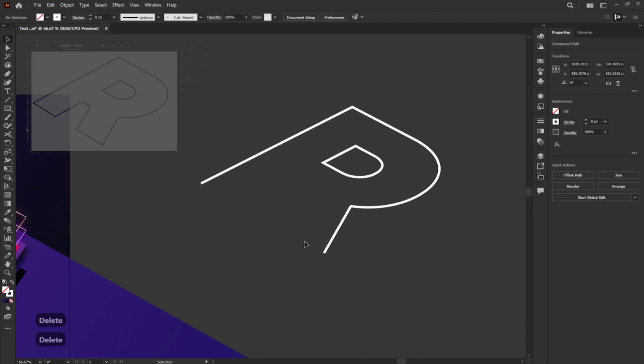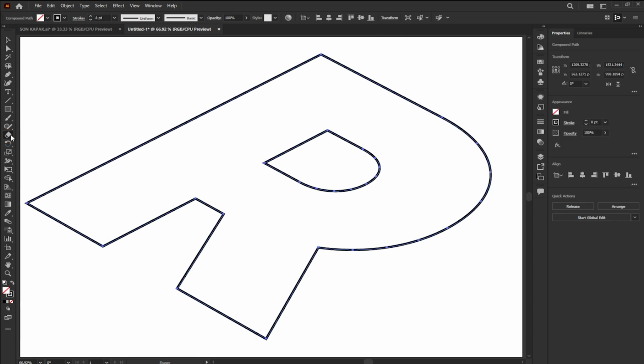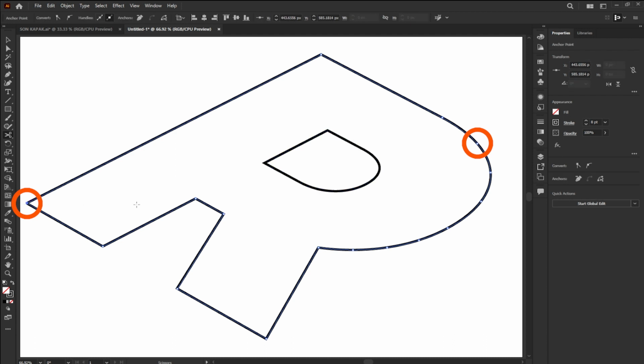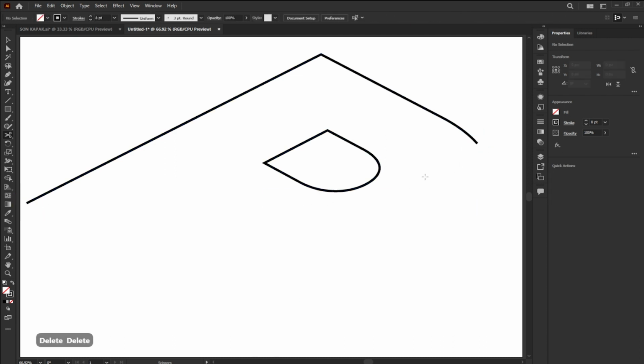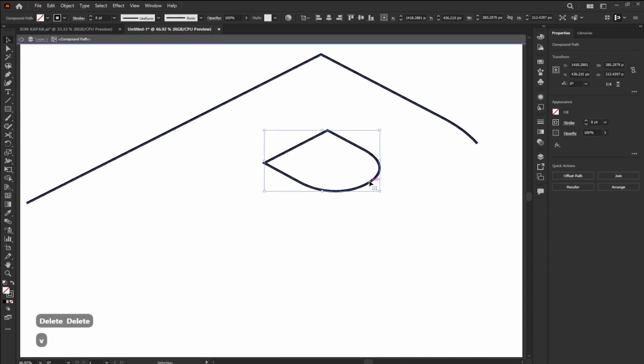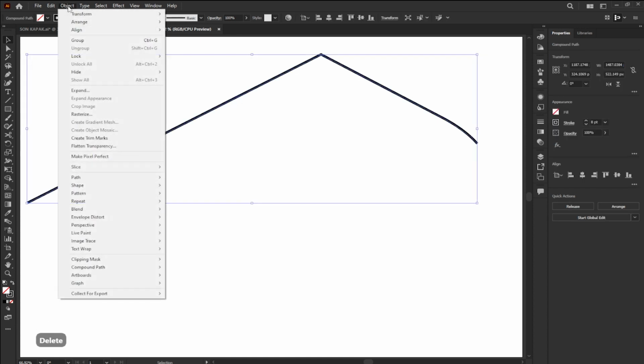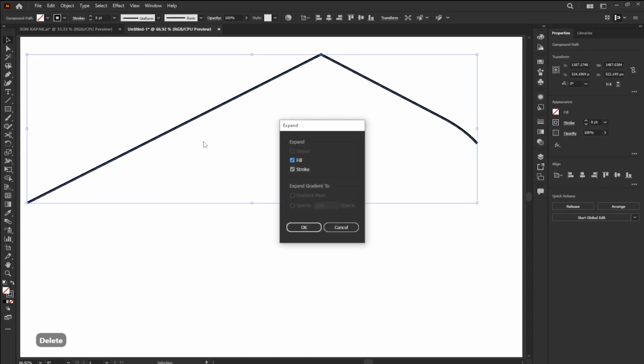We did this wrong. We fix it right away. Select Object, click Eraser tool and select Scissors tool. It is enough to click on the points we want to cut once. When the line to be deleted is selected, we can press the Delete key. Press the V key and left-click the remaining piece twice. And delete. Finally, click on the remaining piece and click Expand from the Object menu, and now our object is ready.